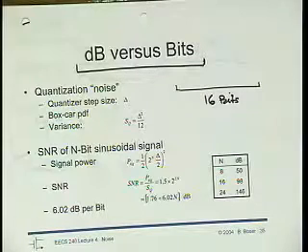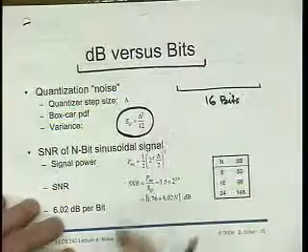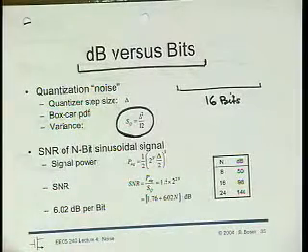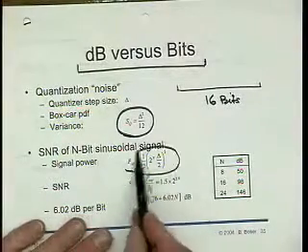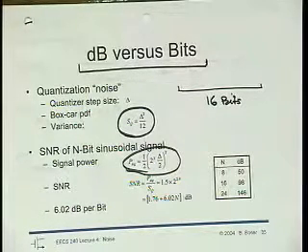That makes an error. Well, that's another form of noise. Not thermal noise at all. It's quantization noise, but noise. And turns out we can also measure it by a variance, right? And now we again can calculate a signal-to-noise ratio. And now we can relate that signal-to-noise ratio to bits.